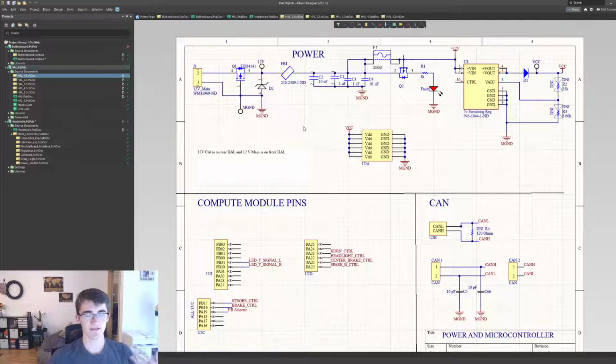As I was developing button board last year, another member of the electrical team, Thomas Gall, was working on the first revision of HAL. So a lot of the general circuit and logic stays the same, but when I worked on the board and managed it, basically what we did is we increased the amount of current that could go through the MOSFETs so that the lights can draw more current and they won't get damaged. We saw an issue with that. And we also changed the board to a 4-layer board just so the different signals could be managed easier.